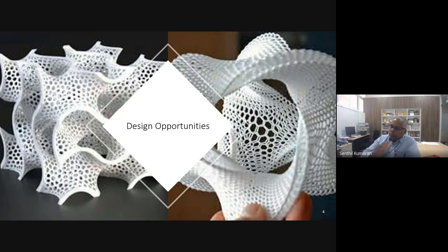to edge, you would see that bone mineral density varies, and the structure of the bone you see in the marrow region is more, I would say, a porous structure, a cancellous structure. And when you reach the edges of the bone, they are very hard and they have good mineral densities. So this we call a gradation in property, or the variation of the property from the center. You see a bamboo column, right? The fiber content varies. The fiber content is minimum at the center, and the fiber content is maximum at the edges.